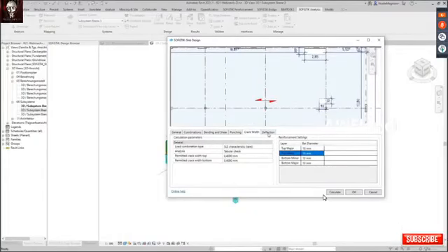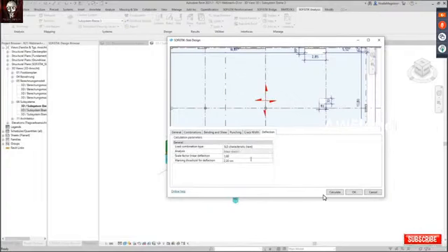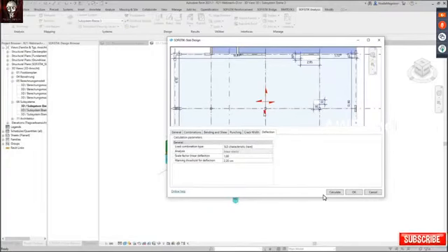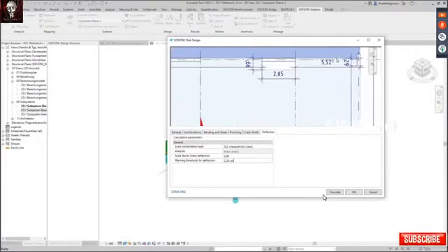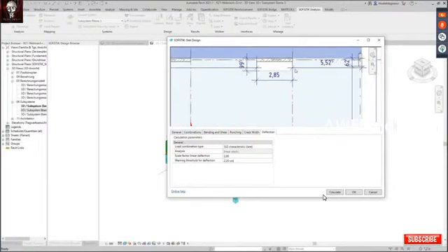And finally, the last tab, which is completely new, is the deflection one. This deflection is just giving an impression of a deflection check. I mean with that it's doing a linear elastic analysis of the deflection. We are not talking about any second order effect or cracked or nonlinear. This is really just a linear elastic enveloping of vertical deflection.